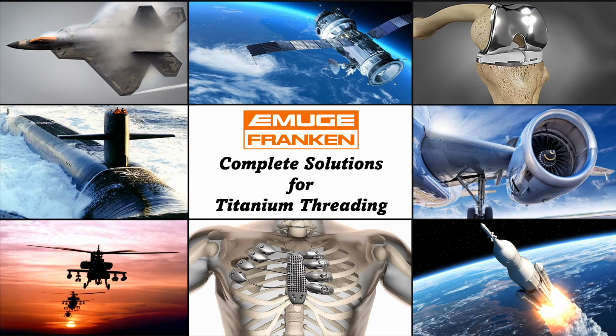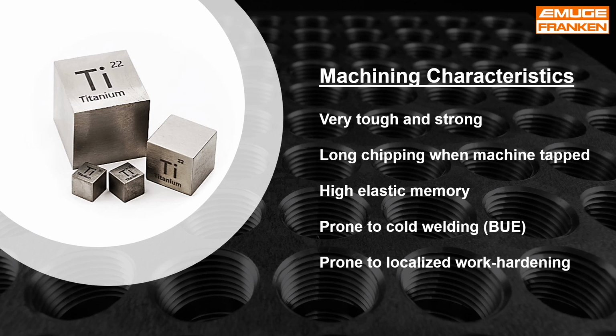Hello, and welcome to the EMUGE-FRANKEN presentation on successfully producing internal threads in titanium materials by either machine tapping or thread milling. To begin, let's review the machining characteristics of titanium as it relates to the production of internal threads. Titanium is very tough and strong. Titanium is long chipping when tapped, and chip evacuation can be problematic. Titanium has very high elastic memory. Titanium is prone to cold welding, resulting in built-up edges. Titanium is prone to localized work hardening if excessive heat is generated in the process.